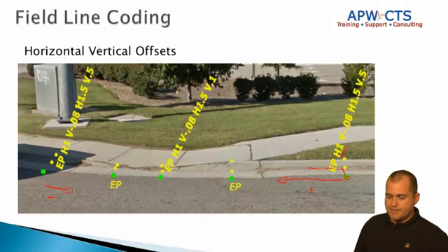Okay, and then I'm doing another 1.5 because I'm coming from this point to pick up that back of curb. And then I'm coming up 0.5, and it's actually probably going to be a little bit higher. Maybe that should be like 0.4, because you're not coming from the flow line. You're actually coming from this edge of pavement point right there. So again, that might not be 0.5, it might be 0.4. But that's the vertical difference. So it's going to create that point.